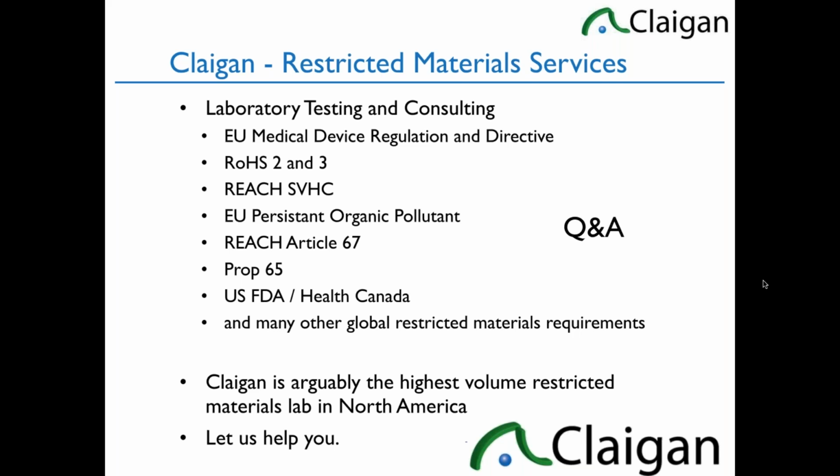Imagine you have a leaded brass standoff, which is not uncommon, holding up your circuit board inside your medical device that's encapsulated, and what's touching is the outer ABS portion of it. Then the internals that happen to be leaded brass do not require justification. They are not invasive or contacting fluids or gases.